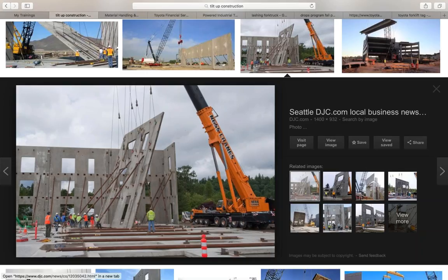And then in addition to that, there may be some important safety precautions associated with tilt-up construction work, right? Tilt-up construction work, folks, like I said, is what you see on page 9 on your right-hand side, and I'm now on page 8 on your right-hand side. So what are we looking at? Workers have to stay clear of the panel while it's being moved, right? Don't stay on the side of it. Definitely don't stand underneath it.